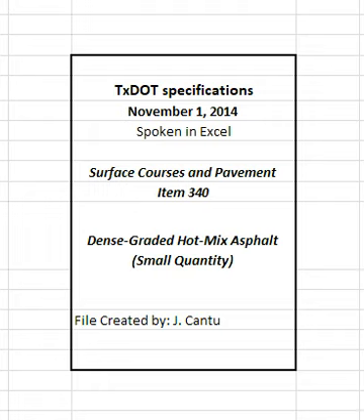4.5 Hauling operations. Clean all truck beds before use to ensure that mixture is not contaminated. Use a release agent shown on the department's MPL to coat the inside bed of the truck when necessary. Use equipment for hauling as defined in Section 340.4.6.3.2, Hauling equipment. Use other hauling equipment only when allowed.